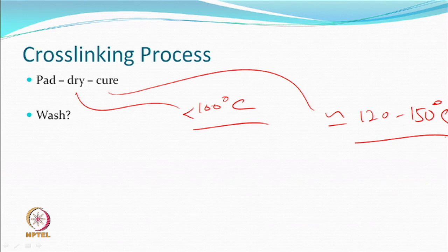So, do we wash? We have to wash. This is therefore different from the normal process of thermo-mechanical texturing of thermoplastics, because in every reaction you can have unreacted compound, and then you have added a catalyst, which is just a catalyst for the reaction, and after that it has no purpose to serve. So, you will be washing, drying. Additional steps may have to be taken if you want to complete this setting process, and then you will do the detwisting.